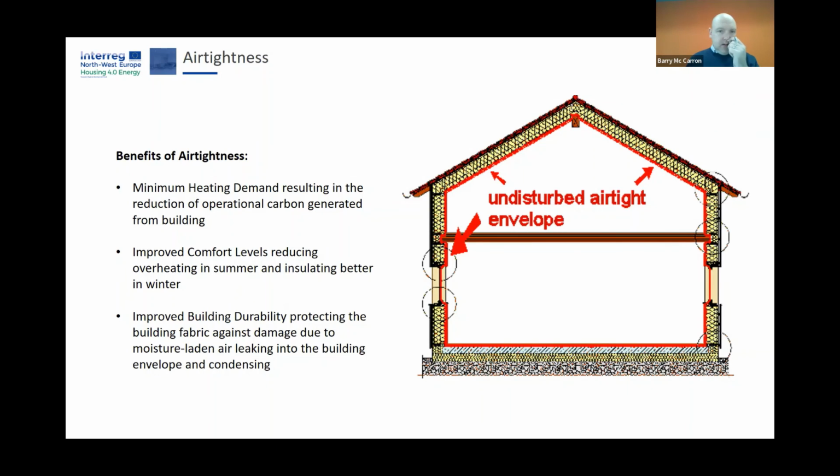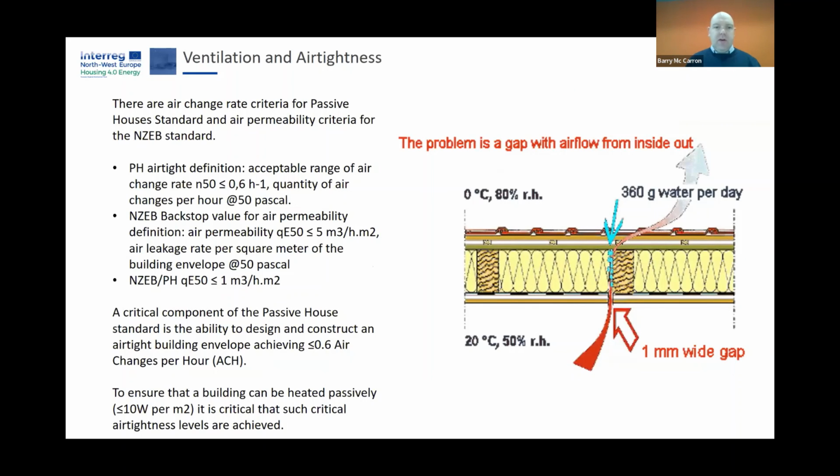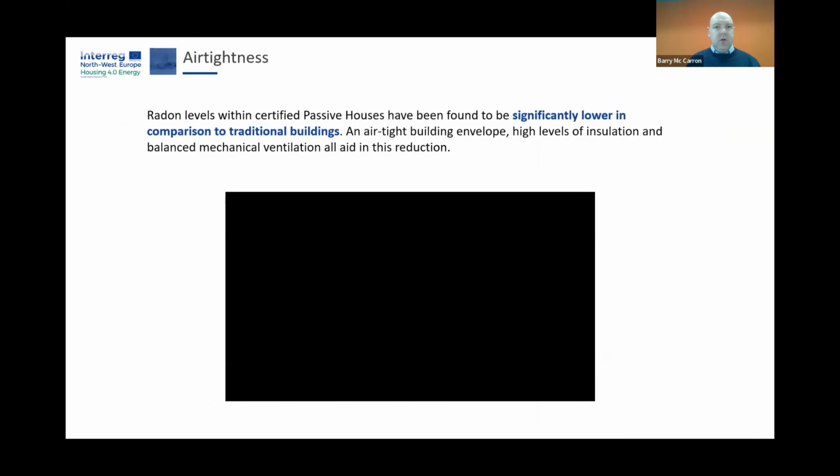But also it's a fast and assured way of protecting your building fabric from interstitial condensation as well, when done correctly. And of course the heating demand. Here's an example of this. If there was, let's say, an unintended hole in your airtight layer, you're into the whole realm of interstitial condensation and having problems. So the dew point of it might be in the wall, and with that you get that condensation occurrence and potentially some structural damage or fabric damage as time goes on.